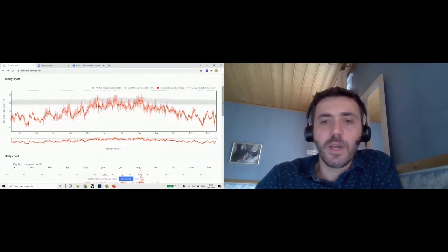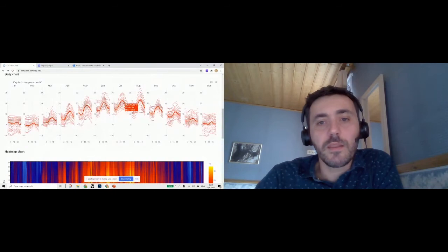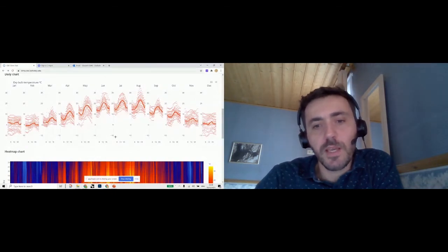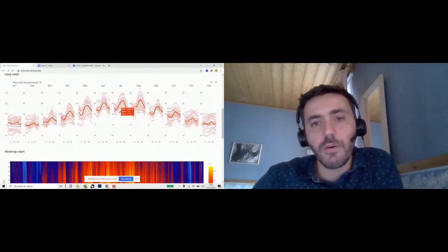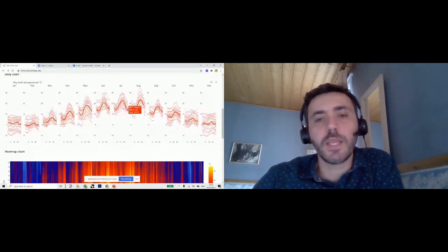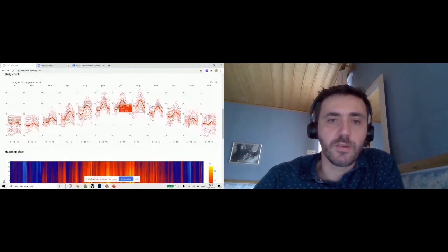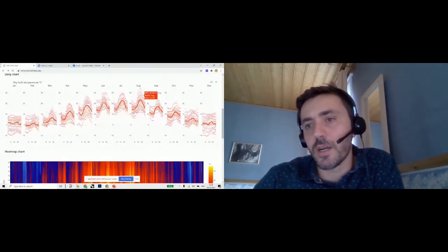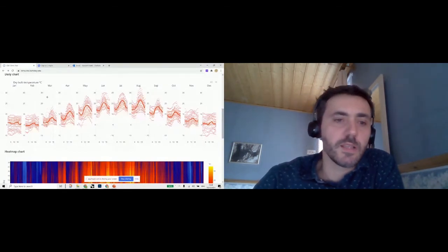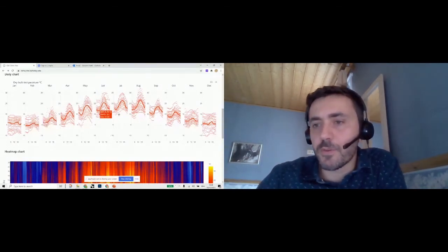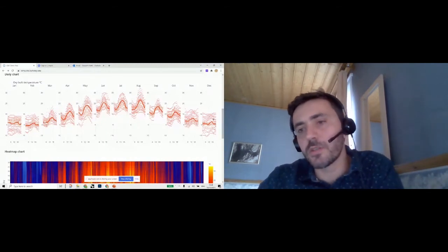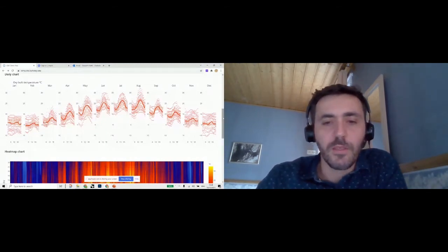And then here you have instead each day of each month. So you start at midnight, go through the morning, midday, and afternoon, and you can see the temperature profile, how it changes, and you have in solid line the typical day, and then as dots you can see the range of temperatures that are perceived. And this is helpful to understand the daily ranges, and things like nighttime ventilation feasibility, or thermal mass.